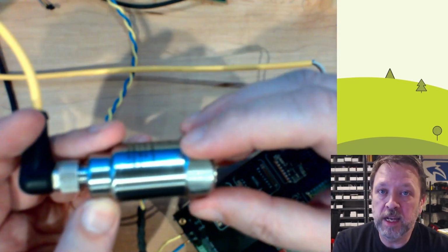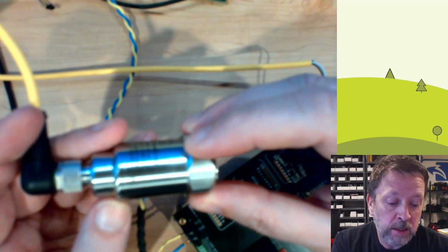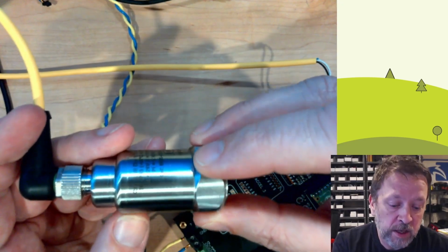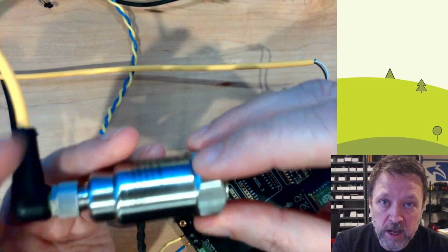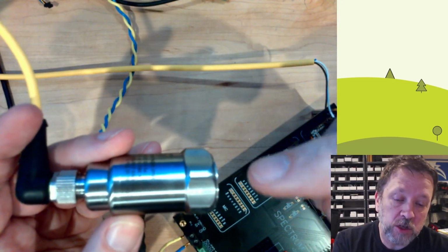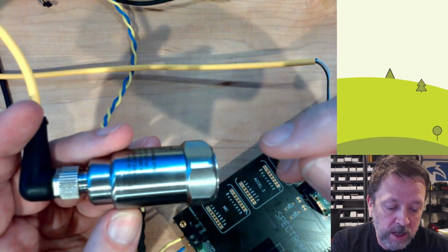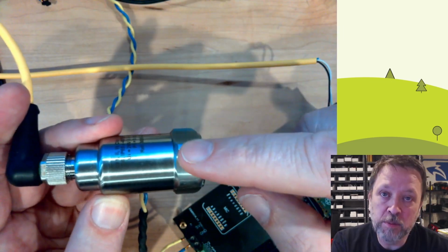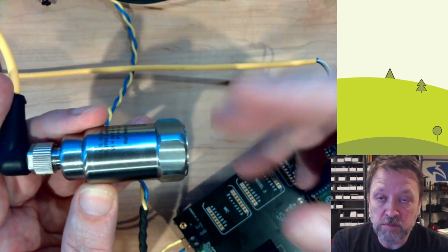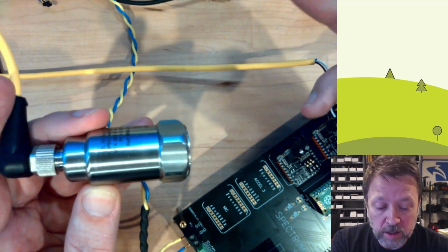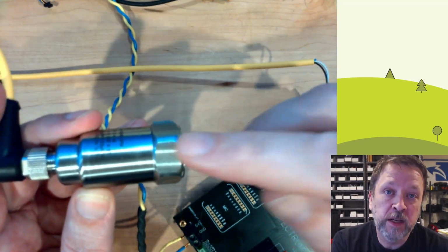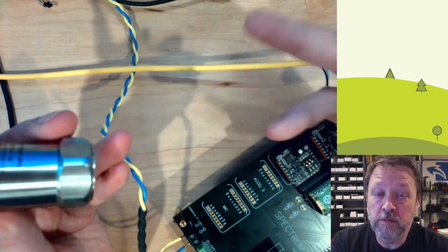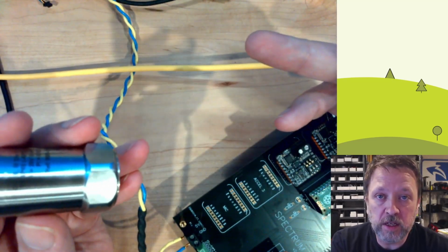We want to be able to detect up to, say, 50 kilohertz vibration. So we need to be able to sample 3 channels at 100 kilohertz due to the Nyquist cutoff to make sure that we can get a 50 kilohertz sample. So how do we create an application or a device that can sample 3 channels, and probably 4, we'll probably want acoustic as well, but let's say 3 channels at 100 kilohertz and still be able to display data and serve data up over something like a WebSocket.